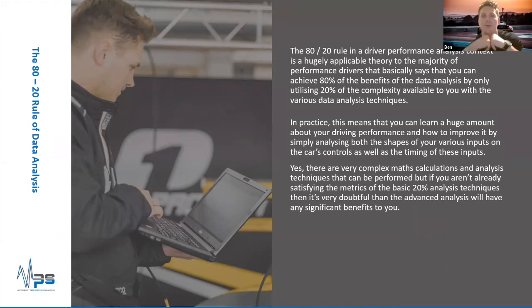In many walks of life, there's the 80-20 rule, which says that you can get 80% of the benefits with only 20% of the hard work, so to speak. And in driver analysis and driver data analysis, that is no different. What that means practically is we can do an awful lot of work in analysing the driver's performance simply by looking at both the shape and the timing of the driver's inputs on the controls. We don't necessarily have to look at the absolute value of the channel we're looking at, but we can learn a lot from the shapes and the timings of them.